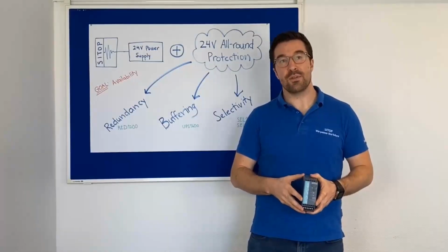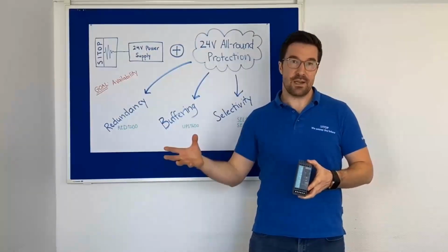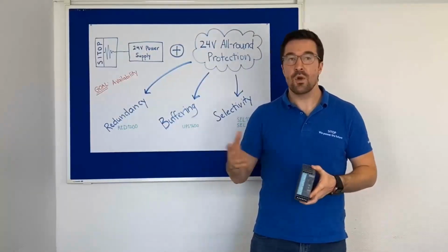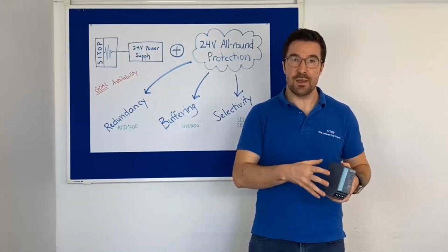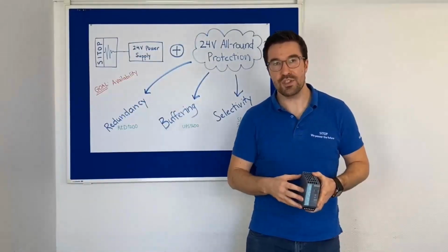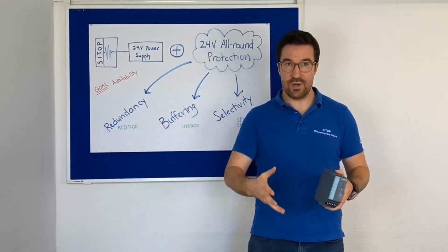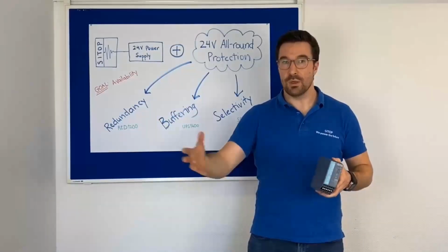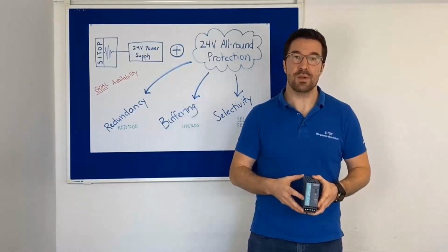So what we have is a line of products. This right now is the UPS 1600, and it offers a secondary energy source, whether capacitors or batteries, that fill these holes in. Now we don't just do 20 millisecond holes, we can cover power outages of up to hours, offering you options whether you want to run your network completely for the remainder of the day, or just simply fill in those small gaps that you might run into.